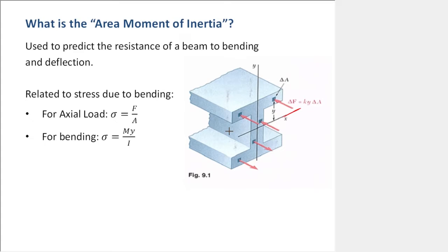There are two types of stress. There's axial stress, which is something in tension or compression, like the bridges that you're designing. And then there's bending stress. Bending stress comes from a bending moment. So all of those shear and bending moment diagrams we've been doing, that's this M right here. The whole reason we're learning that is so we can put that M in this equation. And when we calculate bending stress, we're going to do My over I.